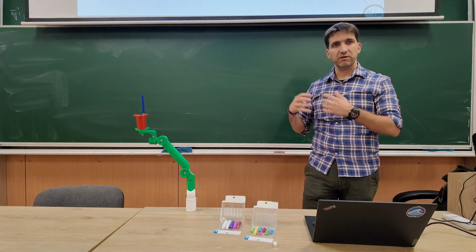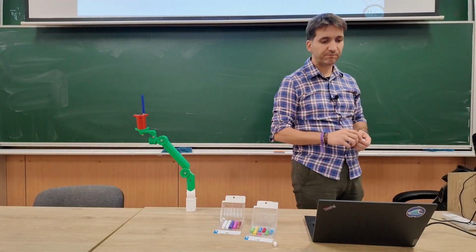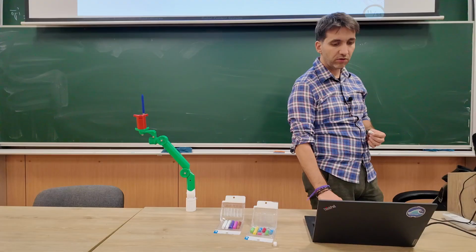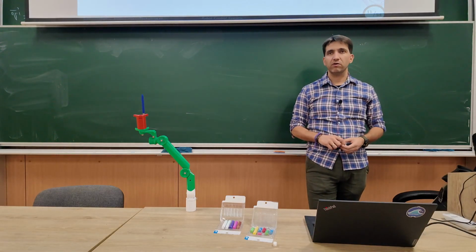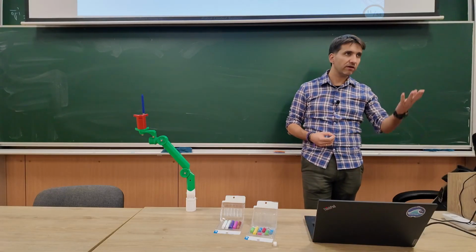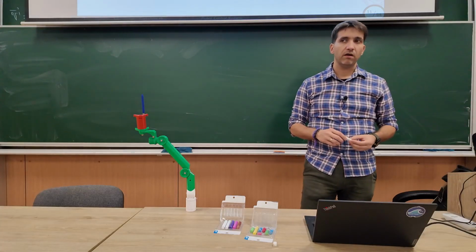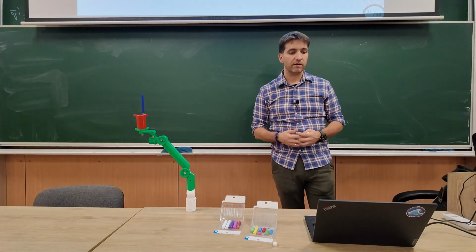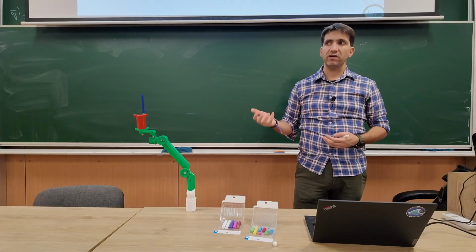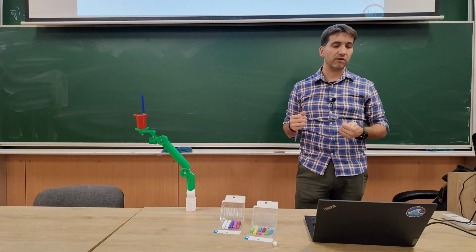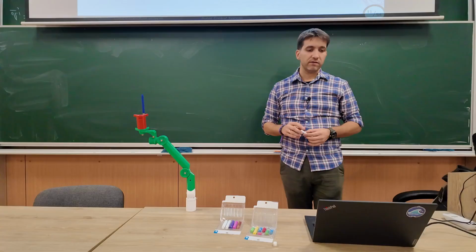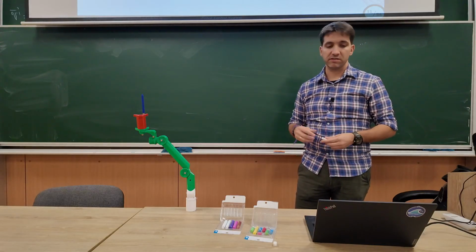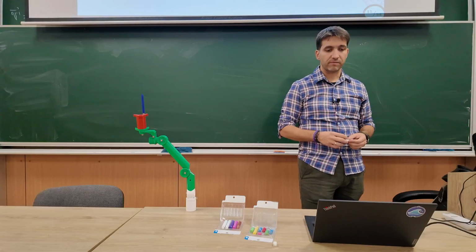I'm not going into all the details, but if you want to research more, that's how you will be able to find it. So here we have this Lagrangian, and I write it as a function of q and q dot. Basically, q and q dot are what we call the generalized coordinates of the system, or you can think of it in terms of state space. It's basically the states of the system. The states that we use for a system are the generalized coordinates, but basically a state of the system is everything we need to know about a system in order to predict how it will evolve. Typically, the states are the positions and the velocities of the system, or the states and the derivatives of the states, for a system, right? Good.